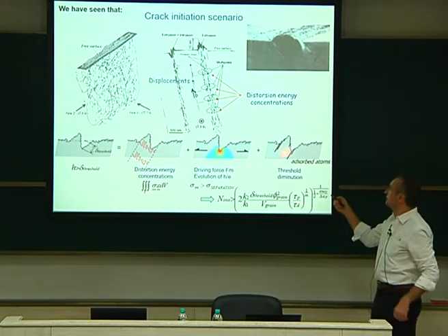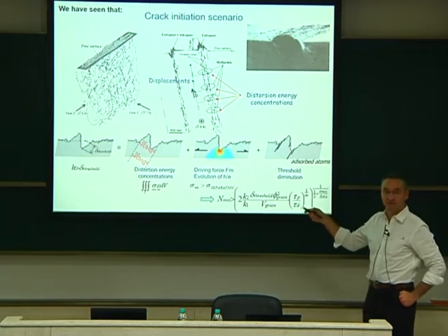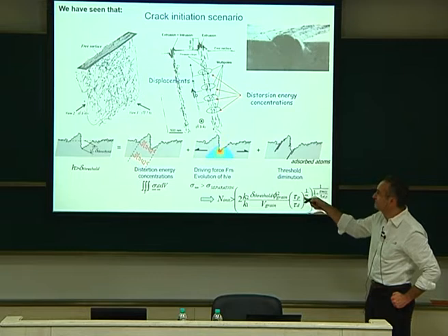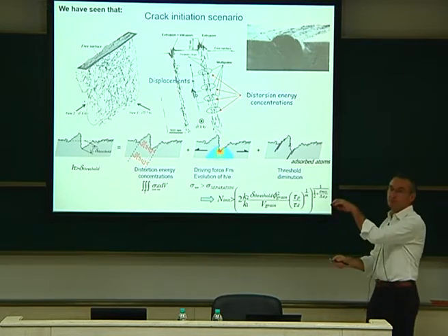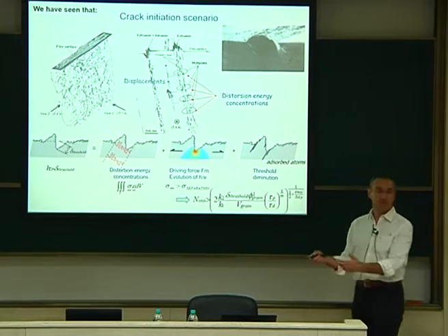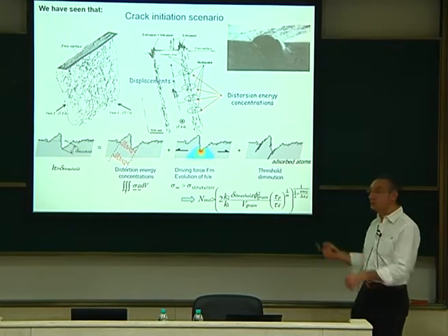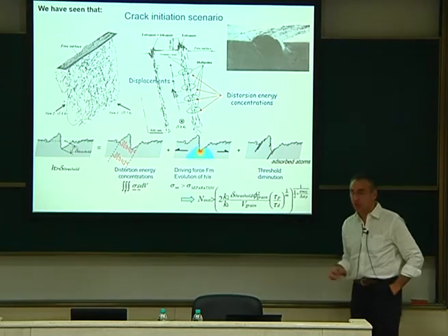And I said, of course, in reality it's even worse than that, because there is much more irreversibility in reality just because of oxide at the interface. Every time you make a fresh step, it should be contaminated by oxygen, and because of that you cannot reverse the step. In my code I do reverse the step, which is quite soft for the mechanism. We can make it better, but it will be again arbitrary rules. Here we didn't want to do that.